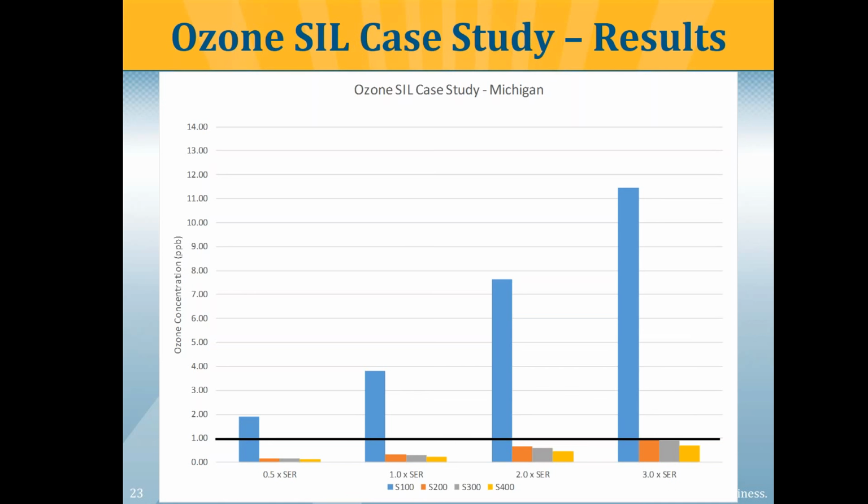Now, unfortunately, once you exceed with one source, you have to go through the cumulative analysis. So if you had a facility where all 4 sources were there, you still had to go ahead and complete the full impact analysis. But if you had only one source which was triggering PSD, then you are okay if you have a higher stack, which goes back to what Dan was saying, that they had to play around with the stack height for that sample project number 2 in order to stay below the SIL.